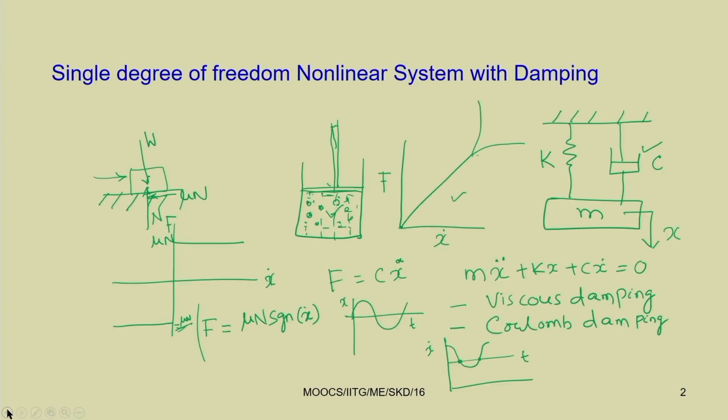In that case, whenever we want, we can change the damping property of the system by applying an external magnetic field. As we are able to change the damping by applying this magnetic field, we can make the damper an active one.